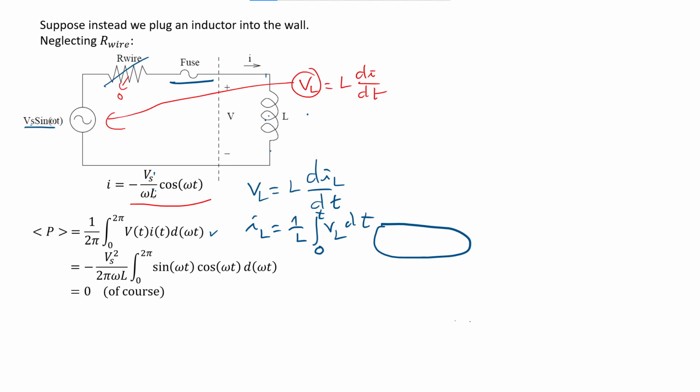So that's why you need to be careful and analyze deeply. Let's say there's no power on the inductor, and you assume there's no current, and then you're careless, you may get your device destroyed, or you may get an electrical shock if you touch it.